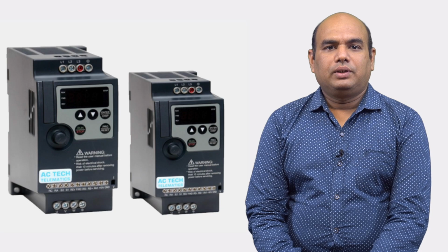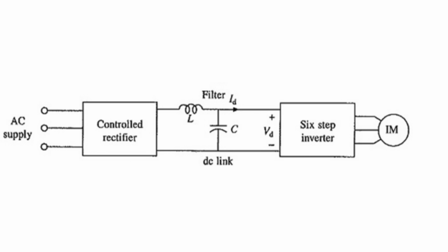Such converters are known as DC link converters. When supply is AC, variable DC input voltage is obtained by connecting a controlled rectifier between AC supply and inverter. A large electrolytic filter capacitor C is connected in the DC link to make inverter operation independent of the rectifier or chopper and to filter out harmonics in the DC link. The capacitor across the inverter maintains the constant voltage.